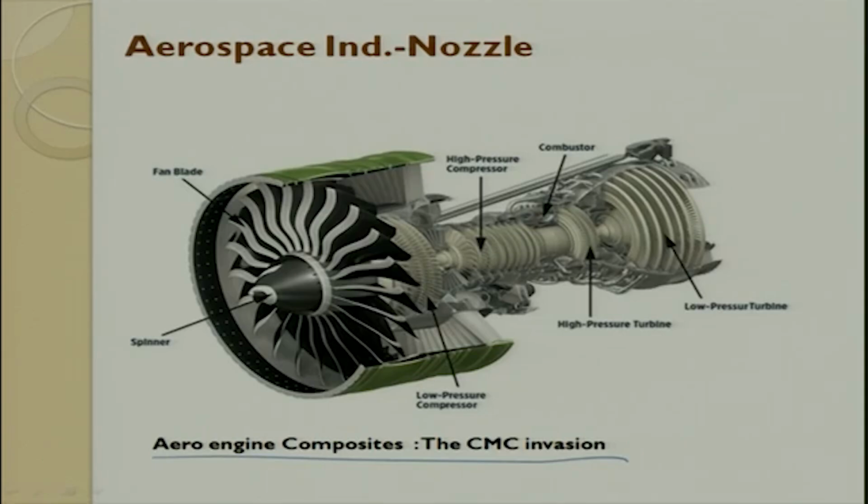So, what they are trying to do is, first they are trying to attack the lower pressure compressor side, and then they are looking at the higher pressure side. Here they will make ceramic matrix composite either as an insert or as a whole part body, right. So, do not think the complete turbine will be made. Either they can make small inserts, for example, a small insert here withstanding very high temperature, or they can also make the whole body. What I am trying to say is, a small portion gets attached to another big portion of the entire system.